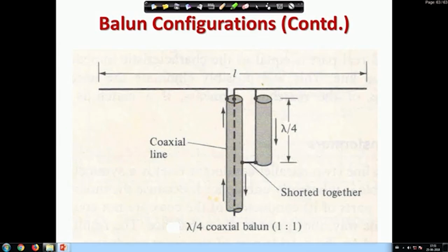We will later see that this common mode and differential mode current concept was cleverly used to design actual VHF TV antennas, which are called folded dipole arrays. One problem still remains: the dipole has a radiation resistance of 73 ohm, whereas free space has 377 ohm.